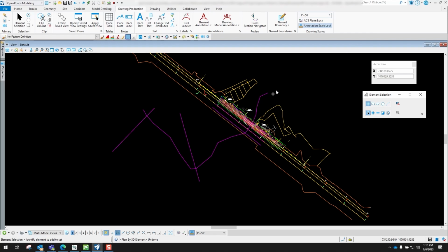And what we need to do first is actually take this valley section that survey picked up, which are these two right here, are upstream valley sections, and then we have our stream bed profile right here that survey picked up. We need to get those into an alignment and also a profile in order to be used to where we can produce those into sheets for doing our bridge survey profile.